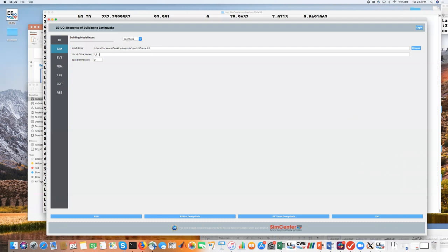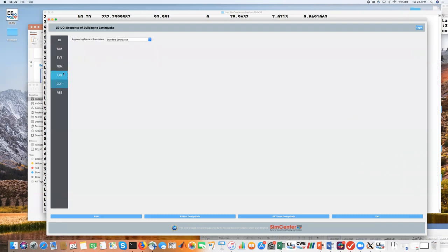Well, you answered the second question there as well. We went on to, does it have application to geotechnical models? So the answer, I guess, there is yes. Yeah. Then more specifically, is there a recorder I can use to get the residual drift ratio from EEUQ? It's not in the standard. It probably should be, but again, you could use OpenSees in the recorder option. Okay. You can specify your own recorder to do that.